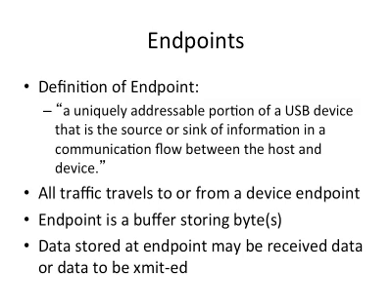So on one side, we know that that's the host, that's the root hub, that's the host device USB driver. And all the USB devices are going to communicate with that host. So on the device side, as we explained earlier, one device may have multiple functions, so multiple endpoints. So we're going to use these as an identifier of the communication pair. We know on one side is the host, but what's on the other side? What's on our device side? We use this uniquely addressable portion to identify that. And the communication could be either into the host or coming out of the host.